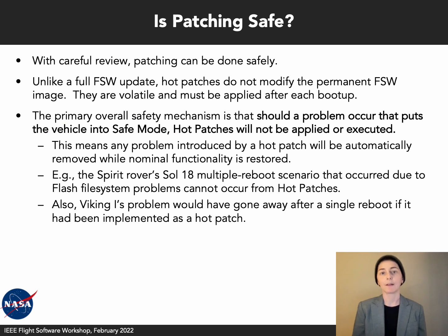Is patching safe? Well, yes, with careful review, patching can be done safely. Unlike a full flight software update, hot patches do not modify the permanent flight software image. Hot patches are volatile. They must be applied after each boot up, and once the computer goes to sleep, they get wiped out. The primary overall safety mechanism is, should a problem occur that puts the vehicle into safe mode, hot patches will not be applied or executed. This means any problem introduced by a hot patch will be automatically removed while nominal functionality is restored.